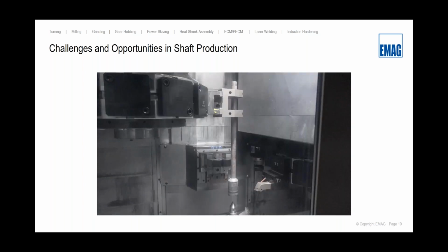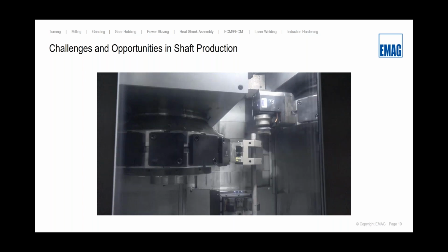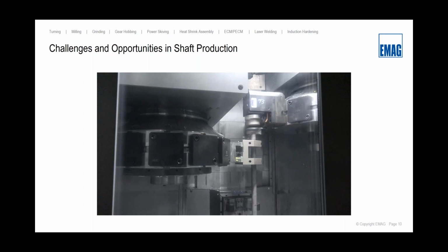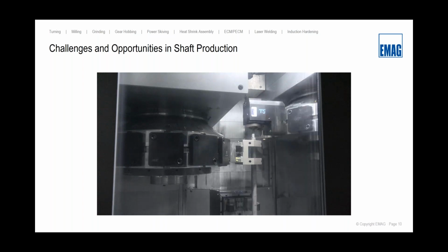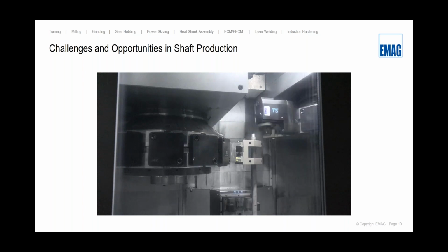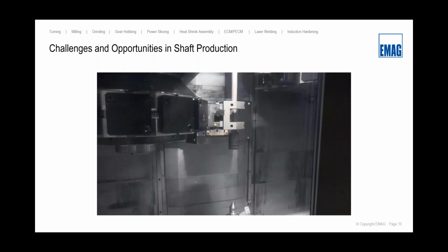So in this case, I have a heavy-duty gripper on my turret on the left, and I'm actually going to hold that part while I do the milling and the centering of that component. Now, to be clear, I'm not taking a huge heavy cut. There's only so much that that heavy duty gripper can do, but you see the same thing. I do my face milling, my centering, and also the hollow milling so that I can clamp on a qualified diameter like I'm doing right now. I hold the part, now I'm dropping my turret down.